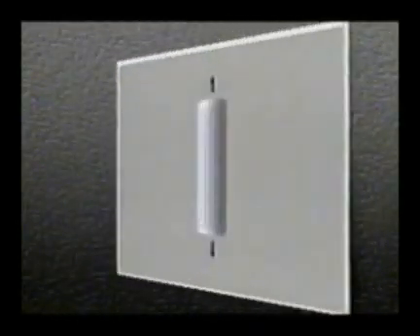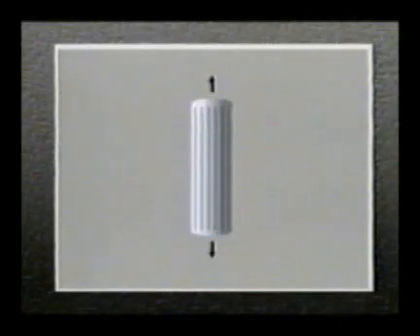To see this effect more clearly, consider the stress lines in a part experiencing tensile loading. Now we will produce a stress raiser by putting a notch in the part. Notice that the lines of stress follow the new contour and are forced closer together, increasing stress at the bottom of the notch. When this condition is severe, it can cause cracks to start.